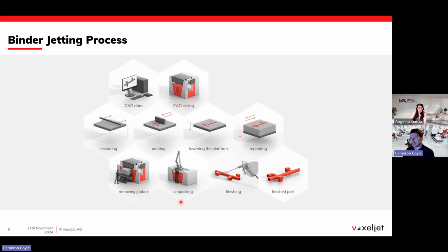And the process in this way offers a lot of flexibility in the design of the castings and also the sand molds or cores, because you're not constrained by traditional means. And that could be draft angles or assembly methods in where you have to assemble them all together. So you can start to print components as single pieces for cores, for example. And this can really take advantage of the technology and simplify the manufacturing process.